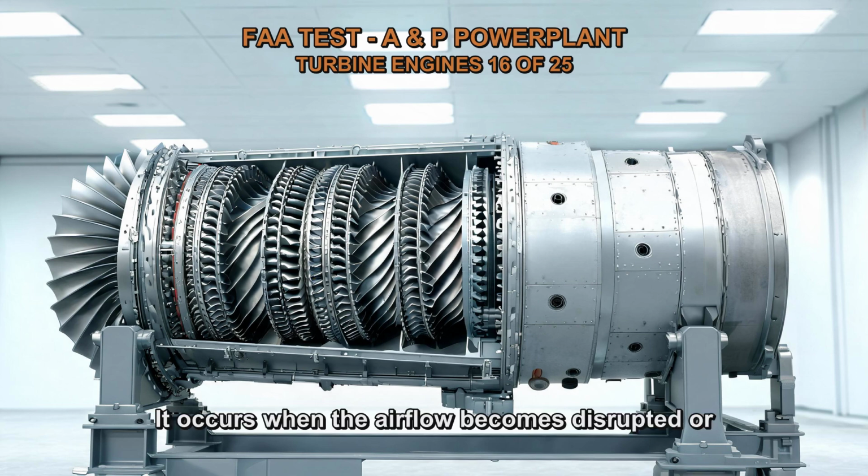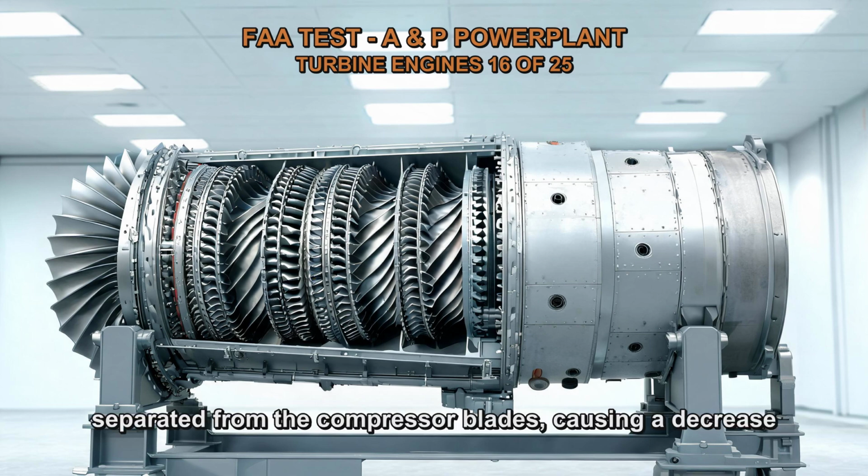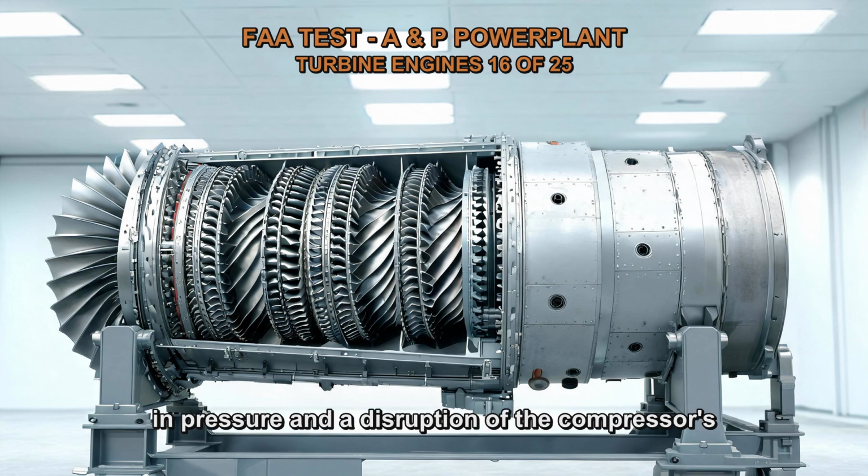It occurs when the airflow becomes disrupted or separated from the compressor blades, causing a decrease in pressure and a disruption of the compressor's operation. By using a bleed valve, a portion of the high-pressure air from the compressor can be vented overboard. This helps to regulate the airflow and prevent any buildup of pressure or disturbances that could lead to a compressor stall. The bleed valve allows for controlled release of air to maintain stable compressor operation.